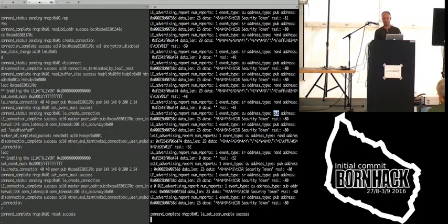The address type is this device has made this transmission using its public address. So the address in the packet is actually the one wired in the ROM on the chip. And finally, there's some data in here which says this is a CSR security token. And finally, the received signal strength is minus 80 dBm, which is not very good. But these are development kits which don't have trimmed radios, so we shouldn't really expect real, product-like performance from these.